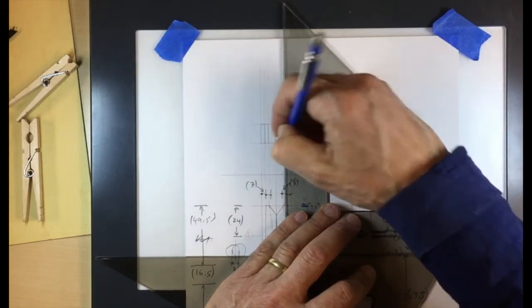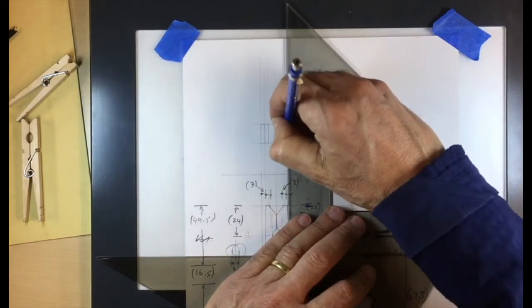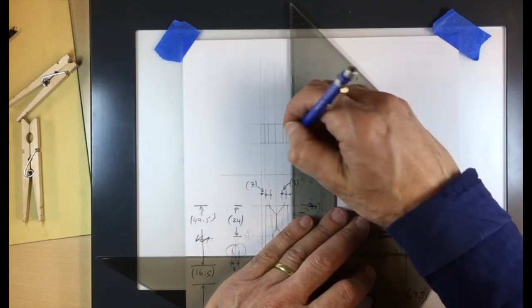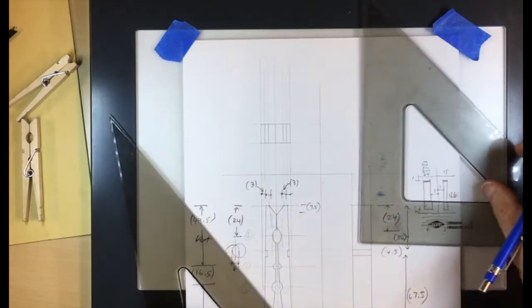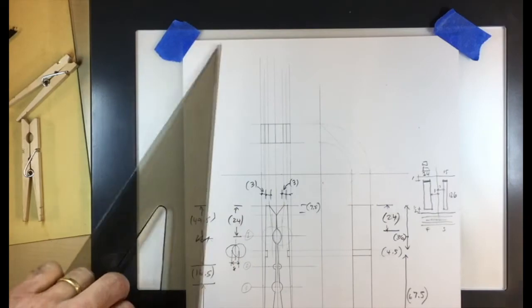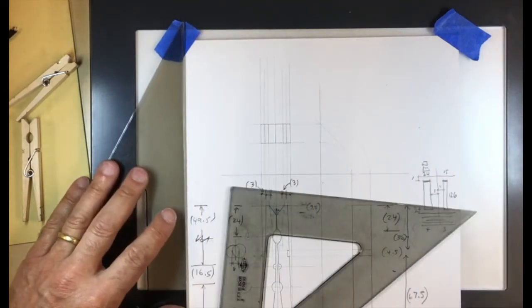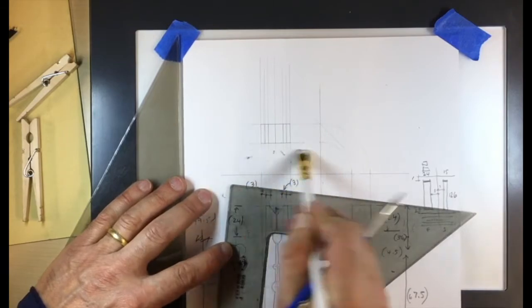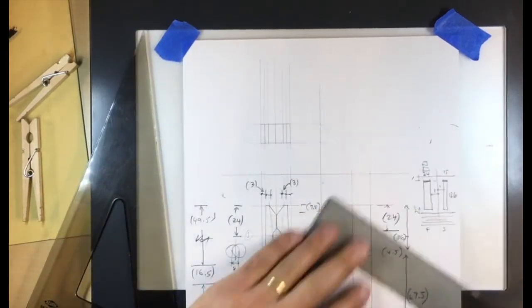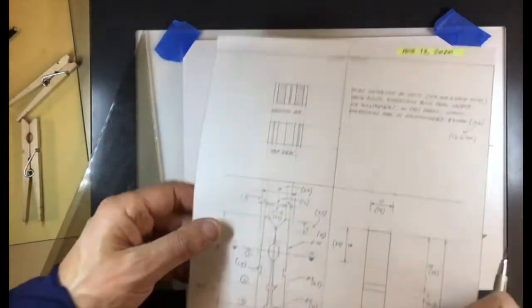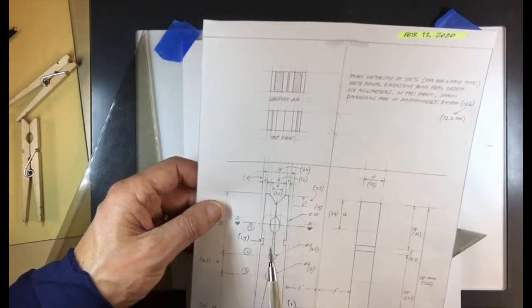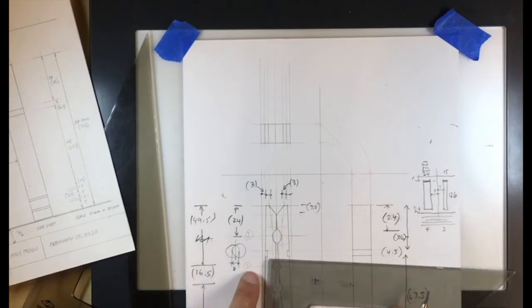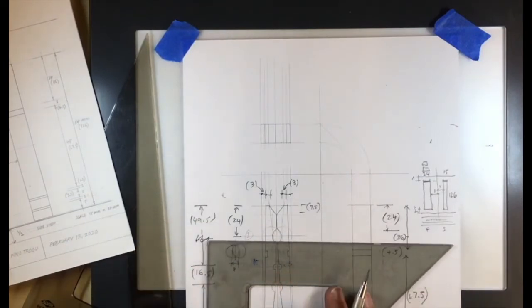So that's the top view, which, by the way, at some point we should label. But let's do that at the end. So, like that. And now the section, we're going to locate it first. We're going to draw it. The way we draw a section line is by a short dash and a long dash, like that.